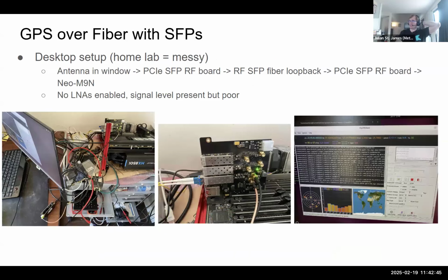I didn't actually need it on the GPS path, but on the other paths I did, because I knew what I was injecting. But if you're designing a general purpose board, you probably want to add some filtering after amplifying. It depends on how much link budget you want to allocate, loss to filter, amplify back. Cool. Now I'm going to go do this.